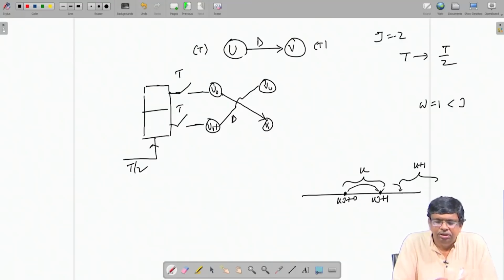Now, you see, originally I had a delay in the edge. So, the two nodes U and V, their timings were not getting added, because they are not coming in the same cycle. There is one cycle it does the job, then gives it here, and then it processes it here in the next cycle. It does not depend on the same cycle here. So, it is doing the job independently. Previously computed job only is used here. So, it does not have to wait till in the current cycle it finishes the job. That is where the critical path was just t.